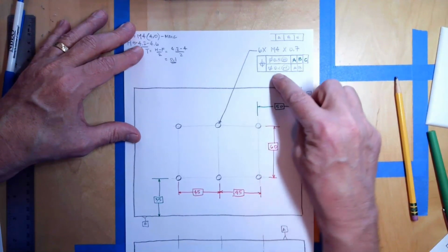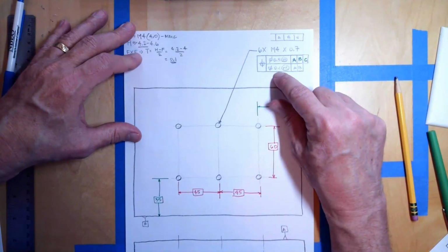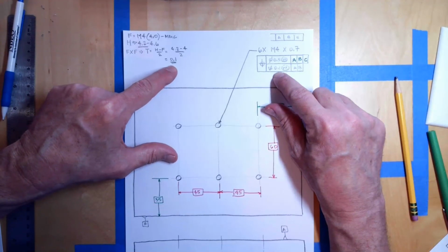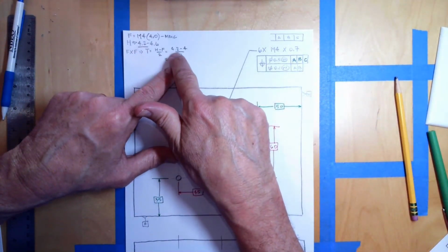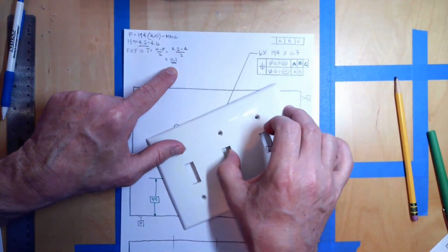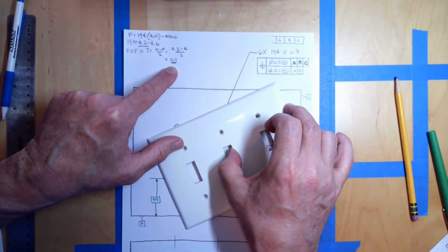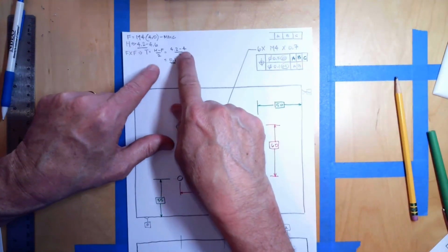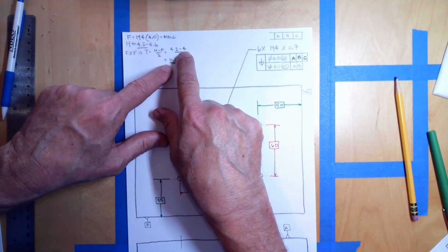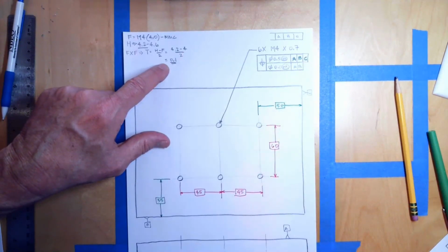And then the feature locating tolerance zone is 0.1, calculated with our fixed fastener equation. T equals H minus F, where the hole size in here is minimum 4.2, so that's the MMC size of the hole. And the fastener is an M4, so the MMC size is 4 millimeters.